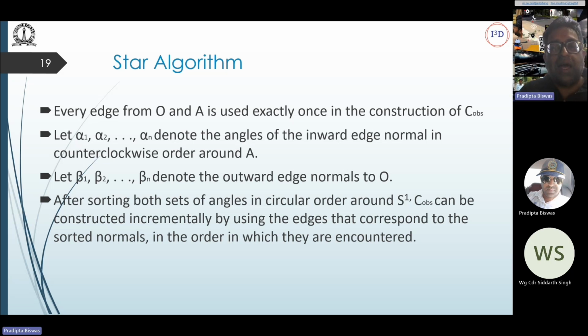We will first consider both our obstacle and the robot or agent to have fixed algebraic shapes, which we can represent by, say, straight lines. Later we can relax this definition, but for the time being, we consider them to have a regular geometric shape, and we will define the normals on each edge which constitutes the robot and obstacle. This normal will make an angle of inward edge normal in counterclockwise order. So we'll consider a specific order, and similarly we'll draw normals to the obstacle as well.